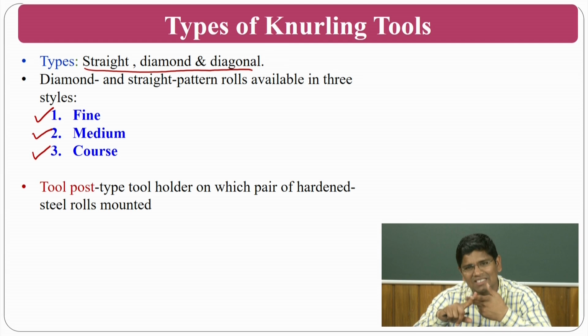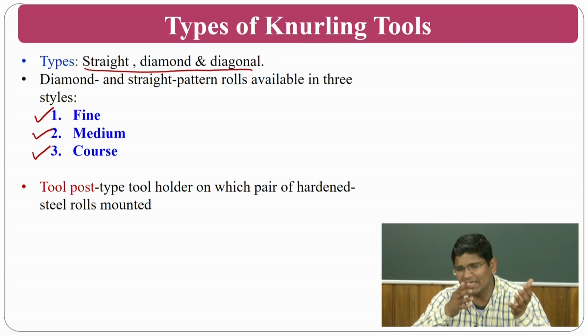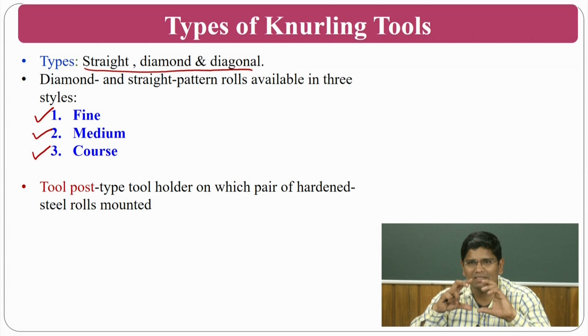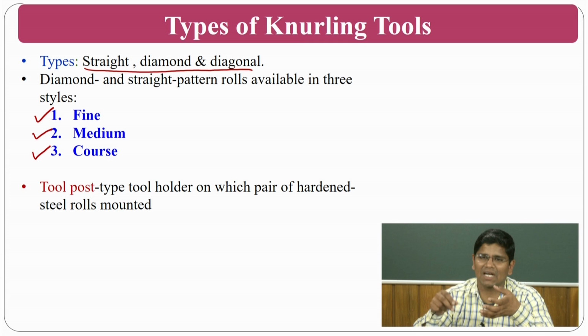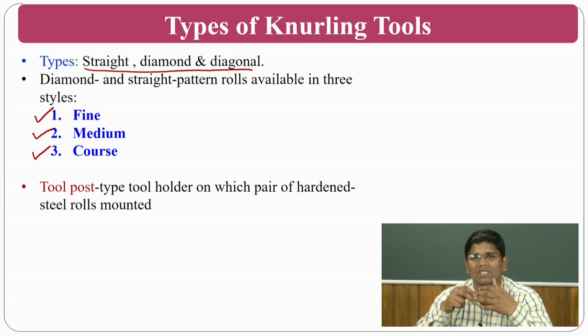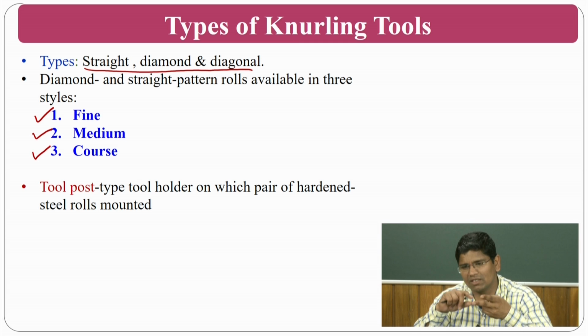The second thing is you can generate the knurling operation, then you can cut using the machining operation. Normal cutting, versus knurling and cutting, you can see there will be a drastic change in the cutting forces, and the cutting may be easy in the second case. There are certain papers where they generate certain grooves on the workpiece, then they cut. So the cutting forces are gradually reducing. So people can try these 2 aspects as a small part of your thesis.